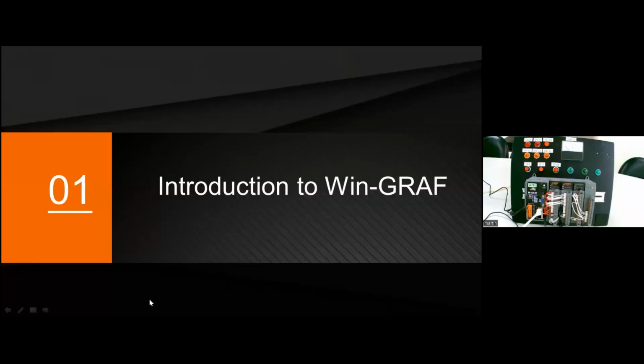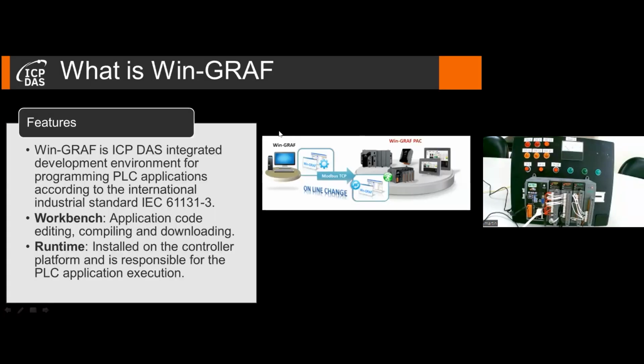Now, a short introduction to Win-GRAF. Win-GRAF is ICPDAS integrated development environment for programming PLC applications, and it meets the international standard IEC 61131. It basically consists of two parts. First, it's the Win-GRAF Workbench, and then the runtime.